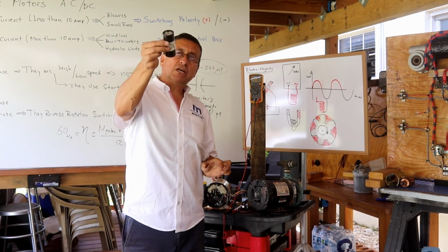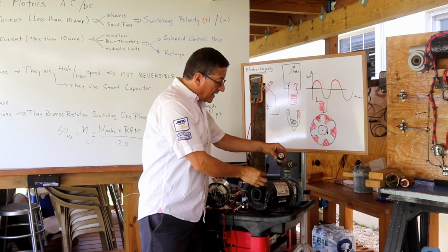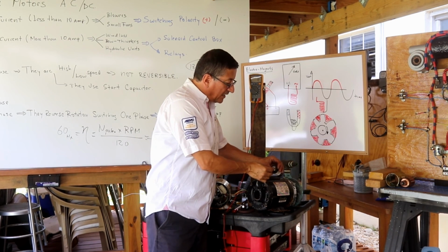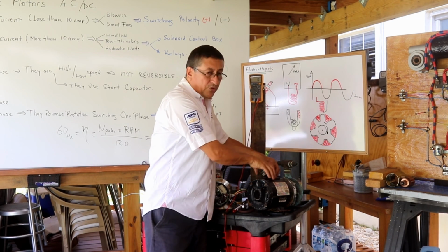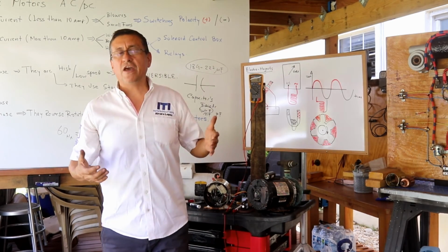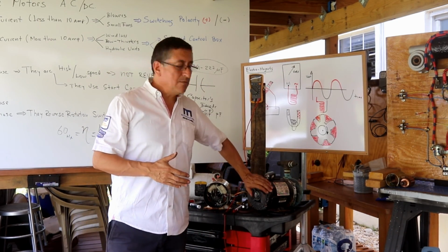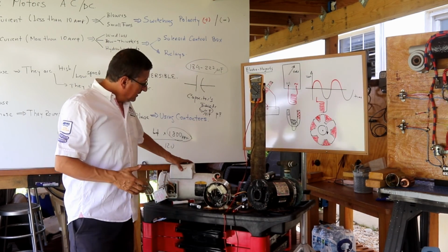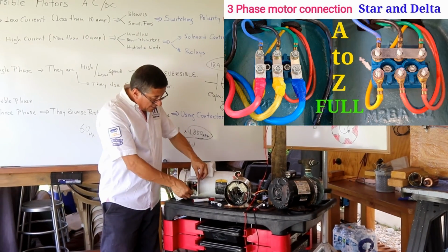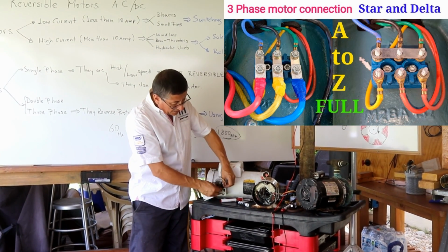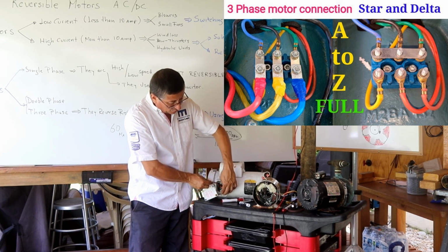Once again, you check the capacitor, the capacitor is damaged, you replace it with a new one, and now you can connect the capacitor again, and you put the cover on, and now your single phase motor is perfect. This is a single phase motor, an AC motor. There are AC motors that are 3-phase, like this: phase 1, phase 2, phase 3, neutral and ground.